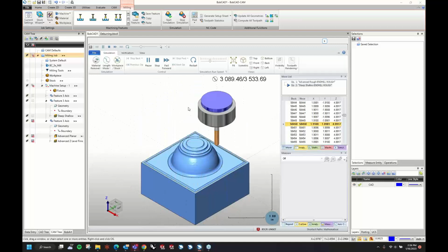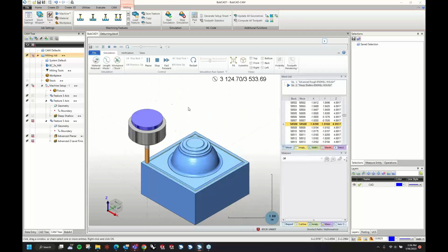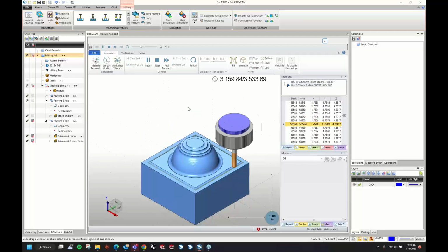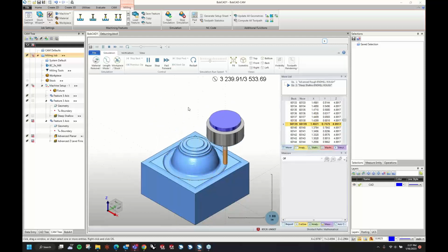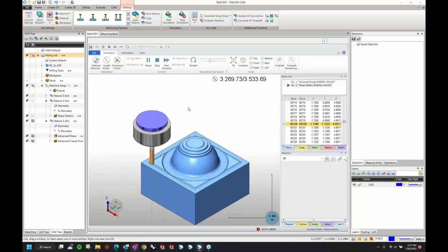Now the equidistance, like I said, taking that bounding box of the area, so it's applying that rectangular path throughout the whole process. It's going to jump around a little bit differently because of the way that it applies. The other thing I will point out is equidistant is all line segments. There are no arc moves. So keep that in mind. You're going to get a lot more code with this. So if anybody has limited memory, you don't have a lot of different ways to mitigate that unless you're drip feeding.